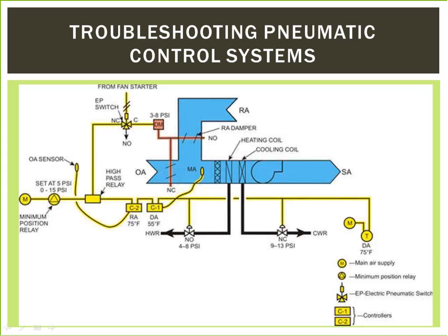In controlling temperature, air pressure feeds a thermostat. The thermostat controls the amount of air that is sent out to ultimately determine the temperature. How air pressure ultimately impacts temperature can vary. The air from the thermostat could feed a pneumatic actuator, which moves the actuator directly in either a valve or a damper. The position of the valve or damper ultimately determines temperature.